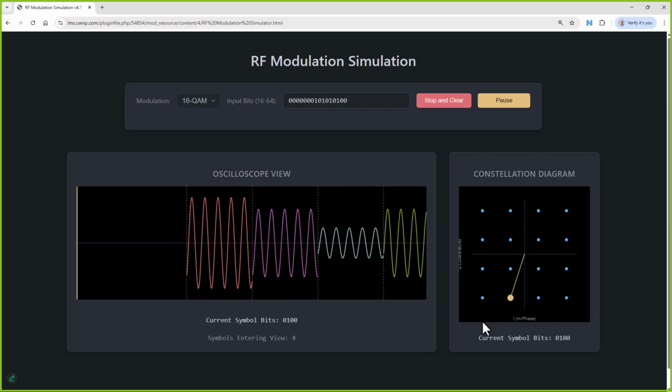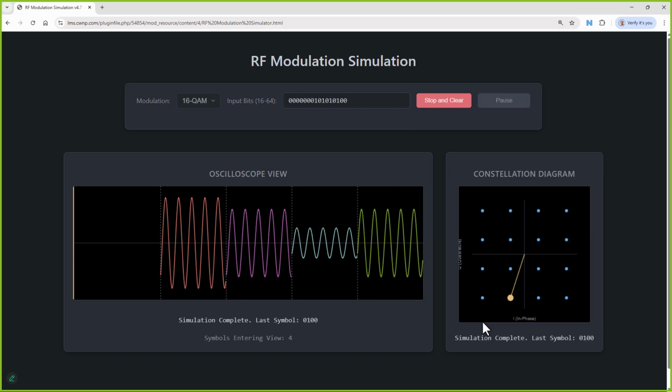Okay. And now you can see that in the modulation, we're not just dealing with phase shifts. In fact, look close. We didn't shift the phase. We shifted the amplitude. Wonder why that would be? Well, it's because we stayed down in that phase. And so we're dealing with amplitude shifts for this communication for the most part. Now, the amazing thing is then just shifting 2 parameters, phase and amplitude, we can get up to this point now where we have 16 possible targets.